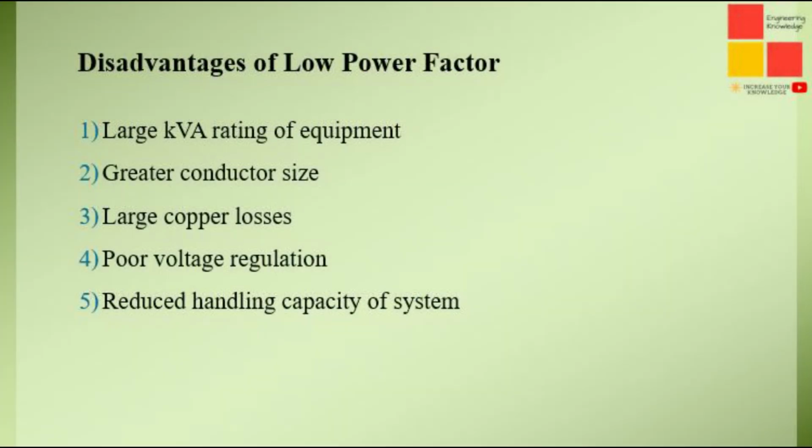Disadvantages of low power factor are given as: large kVA rating of equipment, greater conductor size, large copper losses, poor voltage regulation, and reduced handling capacity of the system.